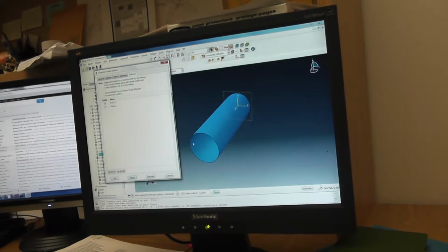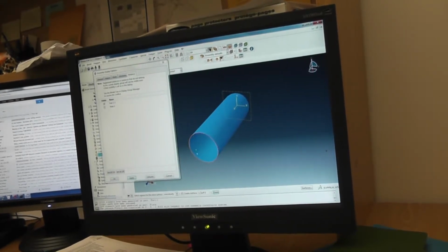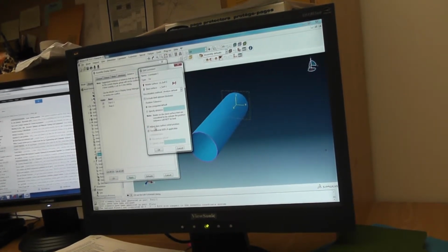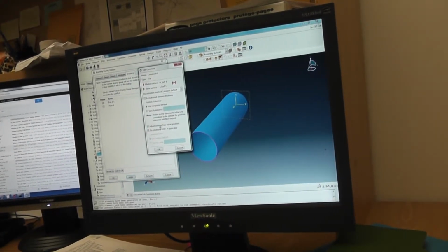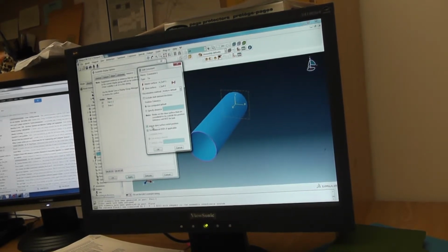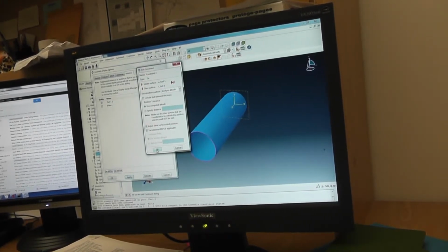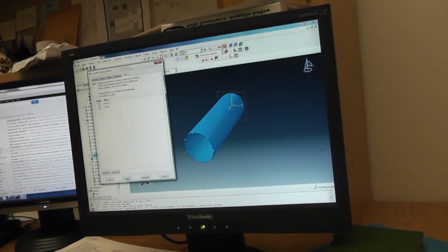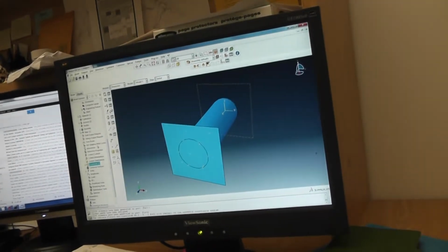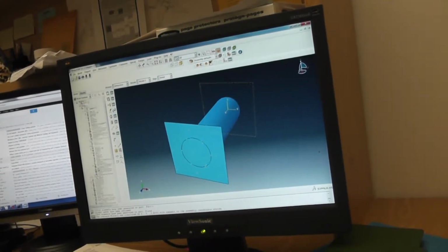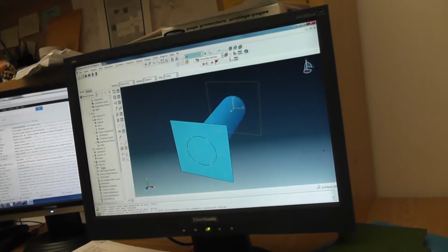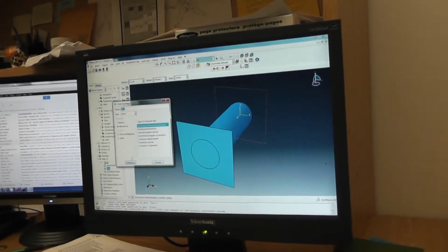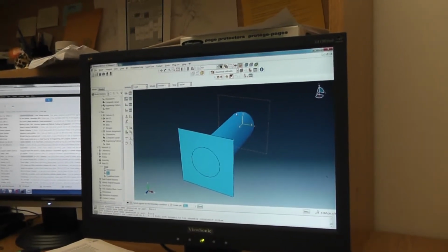and now I'm going to select this and tie the rotational degrees of freedom for the shells if I want, and adjust the initial positions, just make sure that they are tied initially. Okay, and now bring the plate back in the view. Okay. Alright, so now in the steps, we apply our boundary conditions. I have a symmetry boundary condition.